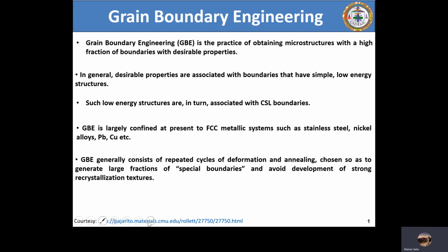So there, the overall boundary energy in a given section of the microstructure is very high, and as a result, when we etch it, there's a huge chance of over etching, which we definitely do not want, because in that case we'll end up having corrosion products deposited at grain boundaries. Although we are able to look at the grains, we don't want such boundaries to be decorated with corrosion debris or corrosion products.